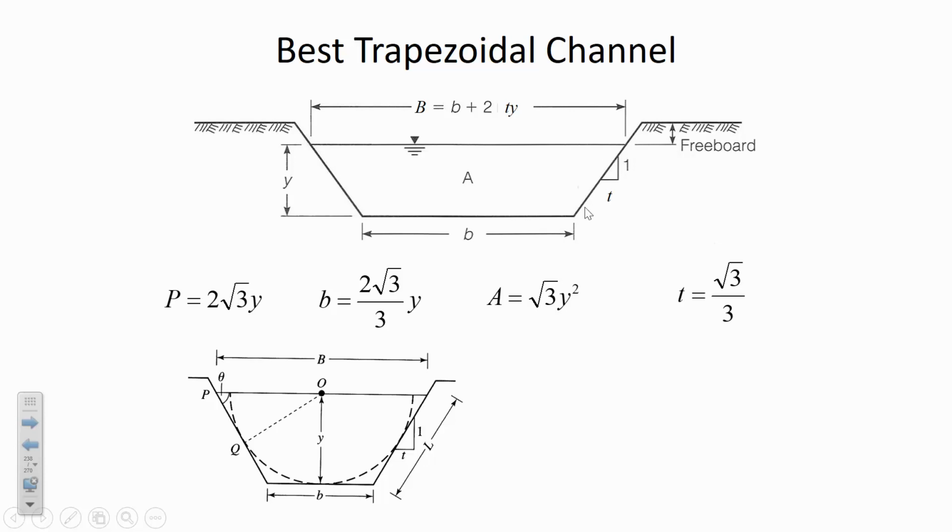So it's so steep that it would be tough to achieve that steep slope with soil, because remember, there is a shear force that's applied on the sides that is going to be greater than the cohesive force of the soil, and so the soil would kind of crumple into the channel. It could be achieved with concrete or rock or metal or wood, any sort of a material that has real strength to it. But you can't achieve generally the best trapezoidal channel, the best meaning most efficient, where you're maximizing the flow rate. You can only achieve it for engineered materials.